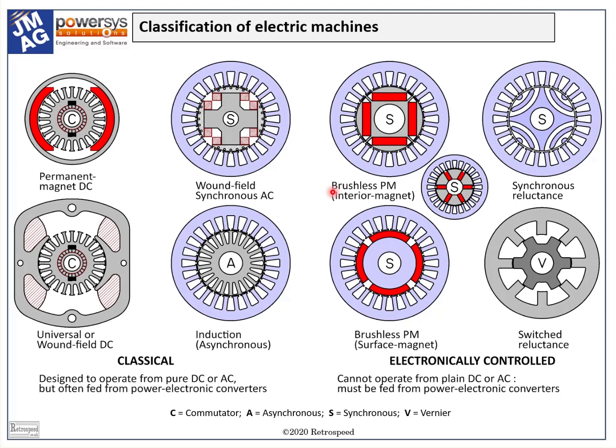From a practical point of view, an important question in this talk is how to drive the motor speed up to high speeds when the EMF generated by the magnet exceeds the available supply voltage. Obviously, that voltage is determined by the voltage rating of the inverter. What is done is to use the inverter itself to drive a negative D-axis component of current, which opposes the magnet flux and reduces the net flux.